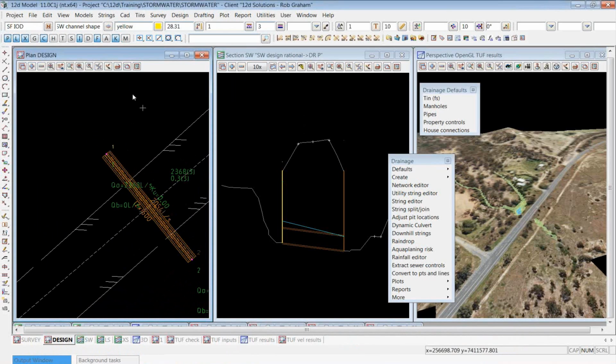What's going to be different when you do 2D analysis is the upstream catchment area is going to be divided into a grid, and that grid is going to create the storage for us. If you thought of it as a very large ice cube tray, it's probably the best way to think of it, with each one of those places where your ice cubes are made being a little storage cell. Each storage cell would hold a little bit of water until it reached the edge, when it would flow over it. We'll take a closer look at that when we go on, but that's the idea: the storage is going to be on the upstream end.